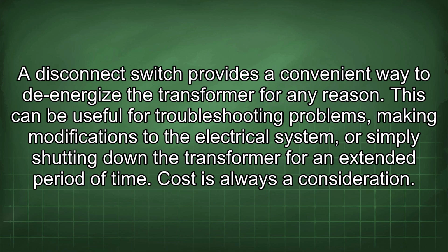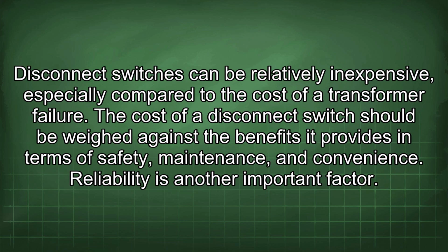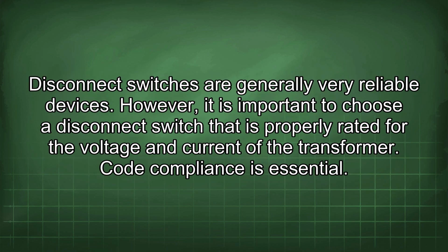Cost is always a consideration. Disconnect switches can be relatively inexpensive, especially compared to the cost of a transformer failure. The cost of a disconnect switch should be weighed against the benefits it provides in terms of safety, maintenance, and convenience. Reliability is another important factor. Disconnect switches are generally very reliable devices. However, it is important to choose a disconnect switch that is properly rated for the voltage and current of the transformer.